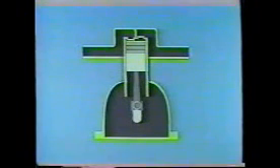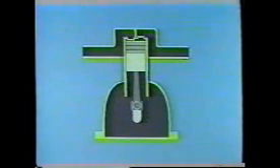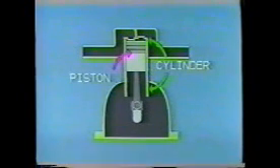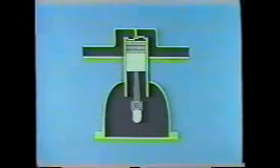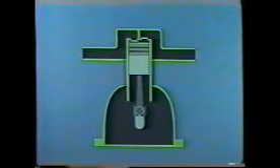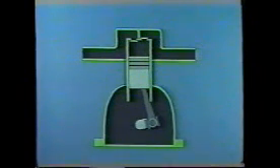Reciprocating compressors work by means of a piston and cylinder assembly. This is a simplified cross-sectional drawing of a piston and cylinder. A reciprocating compressor may have one cylinder and piston, two, or many. There are two valves, one on either side of the piston, that seal in opposite directions. As the piston moves down, the pressure in the cylinder drops. The pressure in the suction line forces the suction valve open and allows refrigerant vapor to flow into the cylinder. The suction valve may also be called the intake valve.